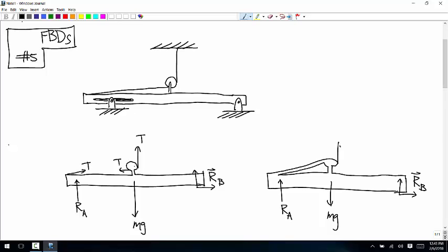There's a cable tension here. But there's no cable tension here or here, because those aren't forces that the surroundings are applying to the boundary. Those are internal now to what we're isolating. So if you thought about it this way, then you're right. I mean, your intuition was exactly right, but if this is what you choose to isolate, then those forces have to be there.